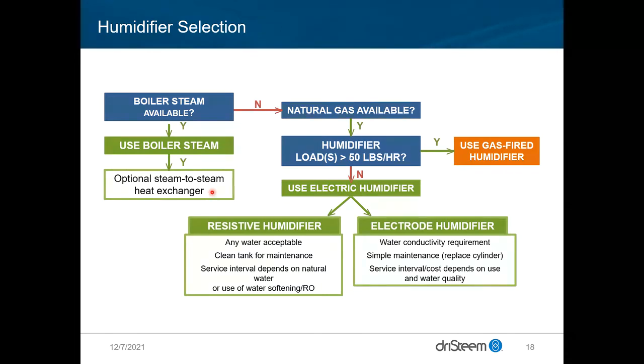So one of the main benefits of using a boiler is that you can have a central system, and since it's at pressure, it can feed multiple zones of dispersion. Once you get into isothermal atmospheric systems, those are not at pressure. Think of them like a tea kettle. So we're going to need to make sure that we have one generator or multiple generators feeding a single dispersion device, because you can't have equal pressures going in different distances.